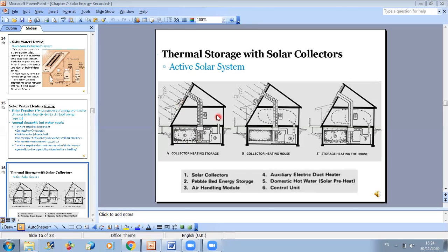Now, once the solar energy is needed inside the space, once the temperature inside my space begins to decrease, then instead of giving the energy to the thermal storage, I can directly distribute the energy collected from the sun to my space, by opening certain vents.